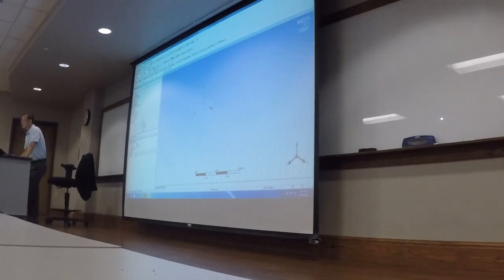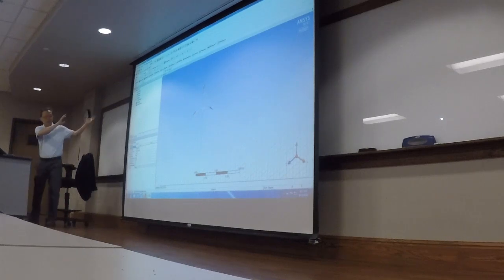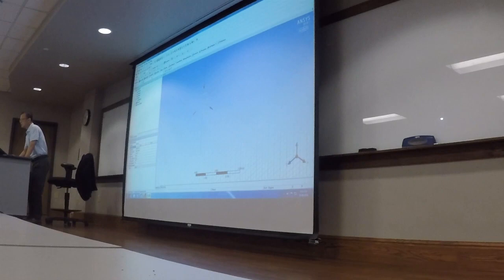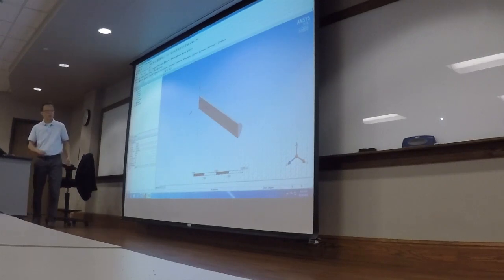Come to the top here. There is one button here. It says extrude. Click on that. All right. So here under the details, it says 12 inches. That's exactly what we want. We want to extrude this geometry for 12 inches. So generate. All right. So this is our line portion of the T-junction.